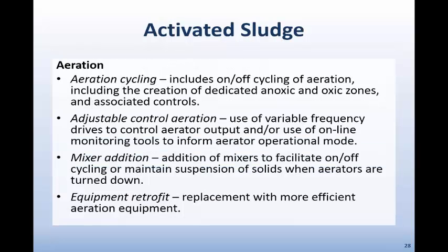So, of course, I saved the best for last. All of our case studies focused on activated sludge, and there are a lot of options available, a lot of things that could be considered for optimizing nutrient removal in activated sludge plants using low-cost approaches. So as we talked about a few slides ago, nitrogen removal in particular is highly dependent on controlling the redox conditions within the process, so that's whether it's oxic or aerobic versus anoxic or anaerobic.